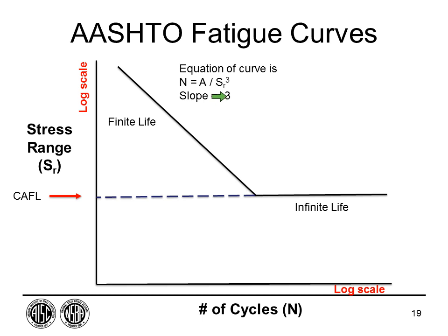This is a very important point. What this says is you can imagine if I had some constant and I have my stress range, the life is very sensitive to the stress range, in fact, cubed. So that means if I double the stress range, if I take a stress range value and I double it, my life, N, decreases by a factor of 8. So it's very sensitive to stress range.